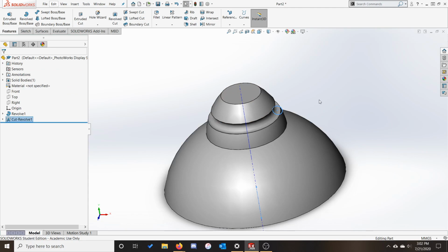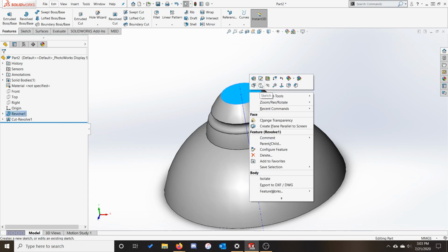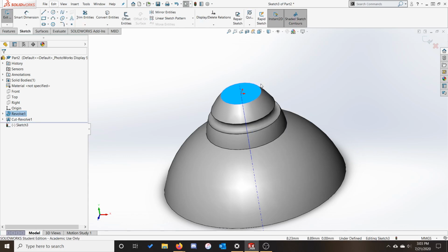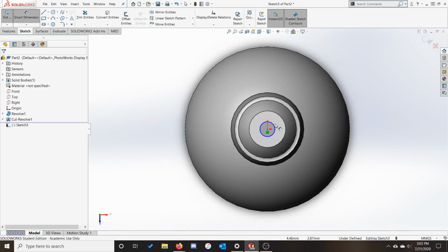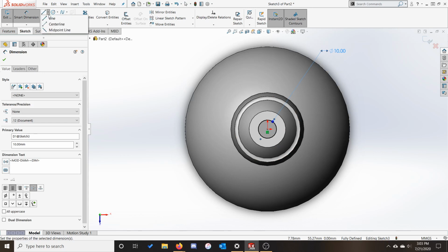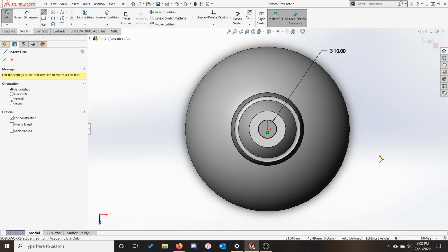Okay, so what about the arc option? Let's say that this lampshade has a hook on top that's made of a cylindrical wire. For these kinds of shapes, we want to leave the profile disconnected from the axis of revolution. In this case, our profile is going to be drawn centered on the top surface of our lampshade. We're going to have a circle here to get our cylindrical wire, and then we can draw our axis of revolution floating in space.